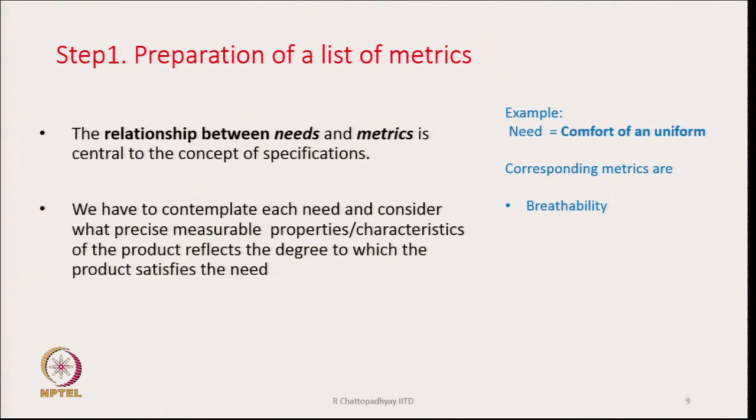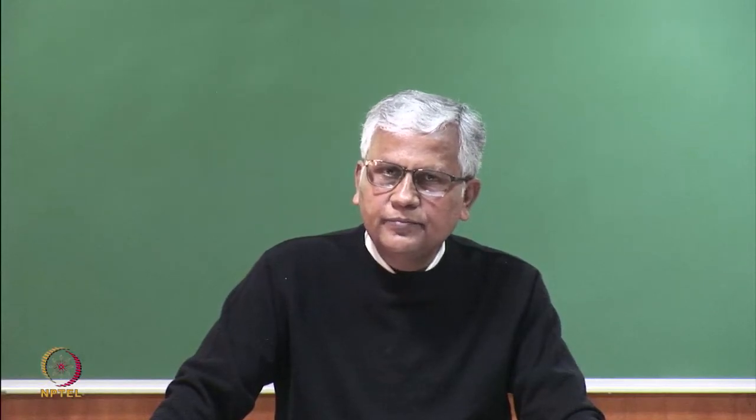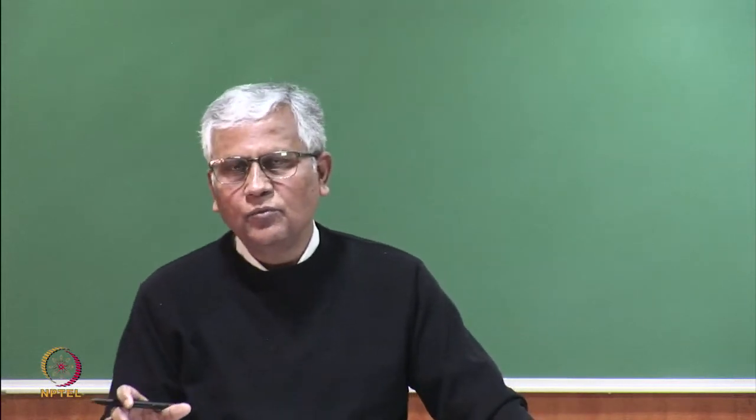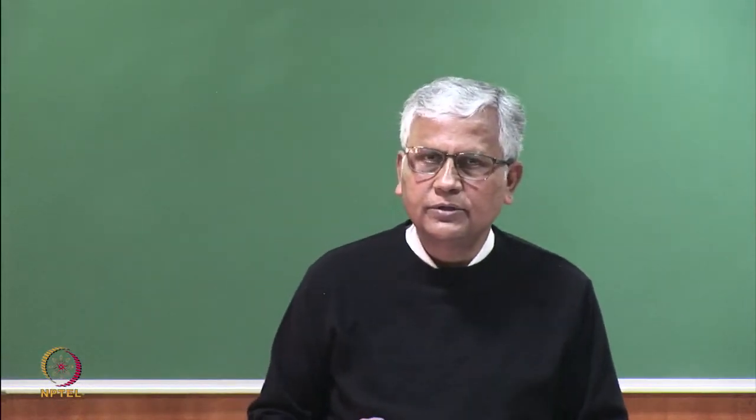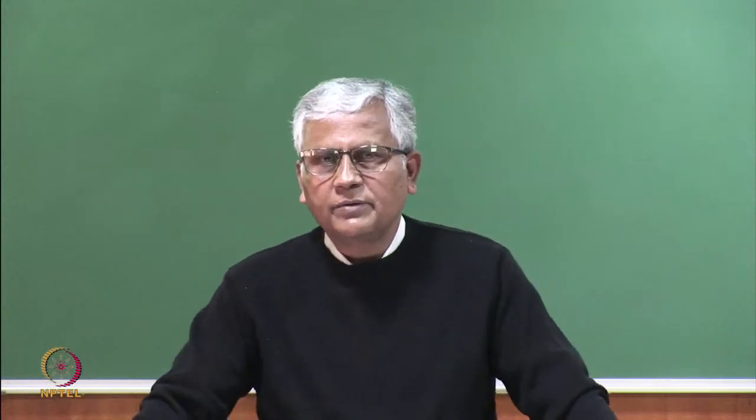Now, this comfort, why is it? Because comfort is a function of breathability. And what is breathability? It is basically moisture vapor and air permeability through the fabric. That is what is basically breathability. So, comfort depends upon breathability, and breathability is a very general term. It is not a really very scientific term. The more scientific term for this is moisture vapor transmission and air permeability through the fabric or through the garment.